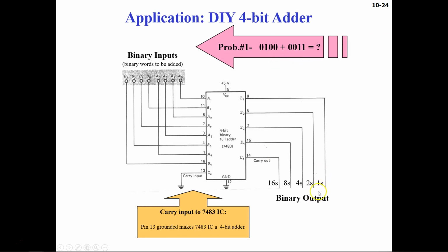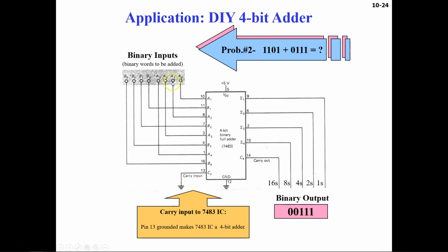So you are going to get 1 1 1, and then you will have 2 zeros. So 0 0 1 1 1. If you add these two numbers here, where 1101 represents all your B's starting from B0 to B3, and then these represent all your A's, A0, A1, A2 and A3, and when you add them up, you should get 10100. So that's the answer.